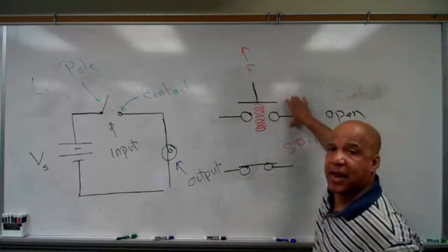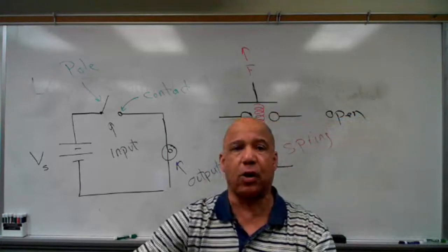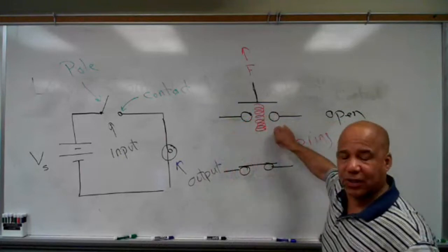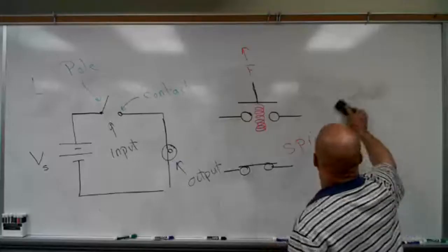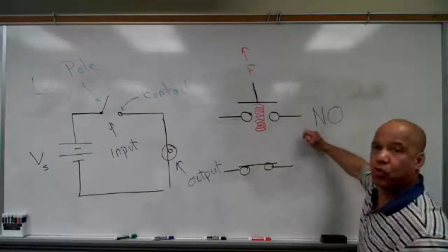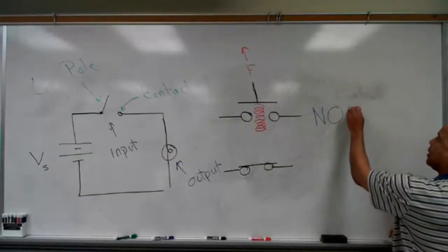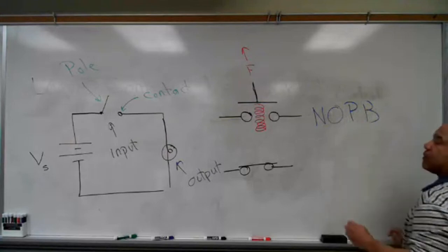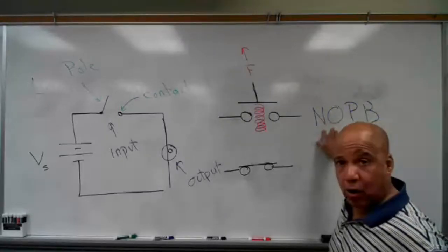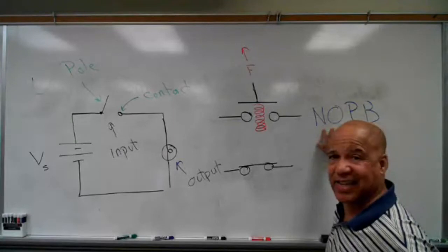So if I lay this on the table with no interaction at all, there's no actor acting on the device, then this switch is open. Or this button is open. So we would call this normally open. That term, normally open. This is a normally open push button. A normally open push button. Now this is really important to understand, this idea of something being either normally open or normally closed. We'll talk about the normally closed thing in just a second.